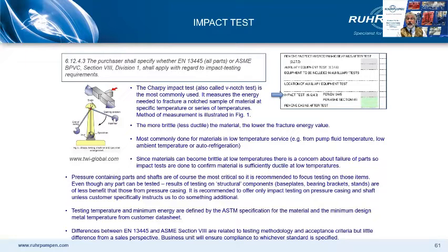Some people ask for it at the low temperature, the cryogenic temperature, which is very difficult to do for two reasons. One, once you've cooled the part down, by the time you've got it in the jig, it's already come up to temperature, up to room temperature again, or close. And the second reason is there's no acceptance criterion. The acceptance criteria given in the ASTM are ambient temperature.